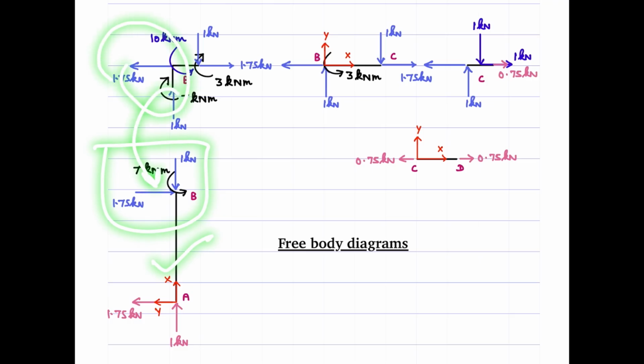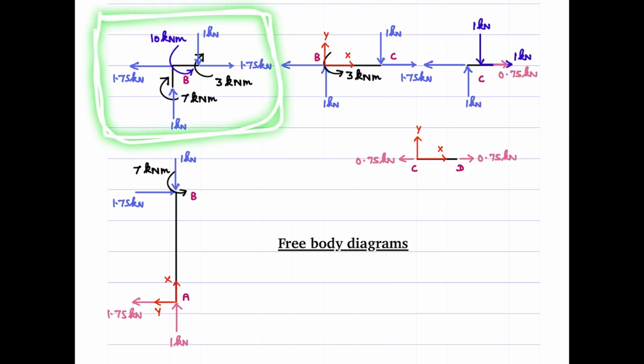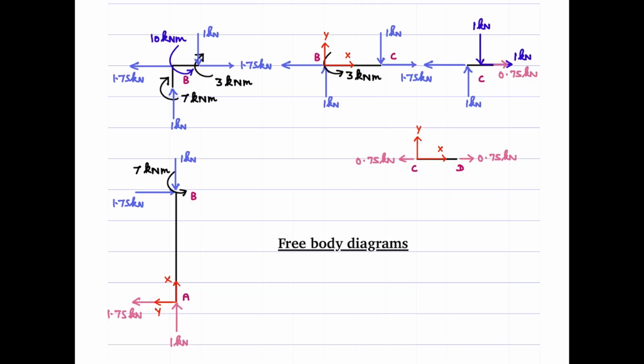Okay, but this is tricky here a bit. See, I have particularly shown the joint B. Why do they do so? Because establishing the moment equilibrium is a little involved here. Usually if the concentrated moment is not present at a joint, it's easy. You don't need to bother much about this joint. So when we move from this to this portion of these two members, I mean AB and BC, it's helpful to consider this joint B.